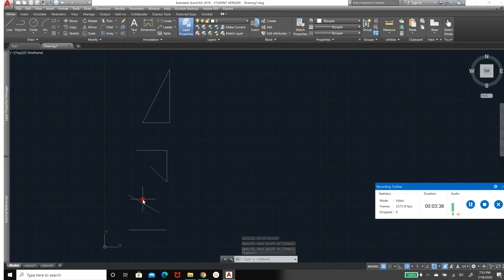So those are some lines, and then to do polyline, you'll either click on the line icon or type polyline or p-line is the shortcut. And it'll, same thing, specify a starting point, so I'll tell it starting point, and then it'll tell me to specify the next point. And remember, I can type in a length or I can just have it snap there.